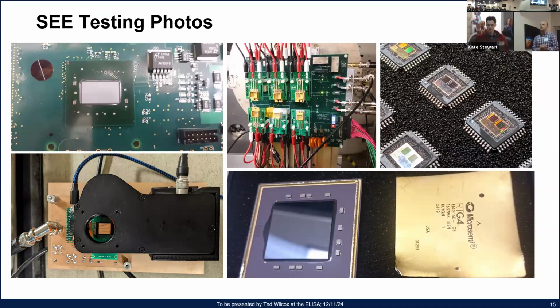At most of our domestic facilities, the energy is such that we can't penetrate the lid of the device. So we tend to delid the devices. We are operating at much lower energies than those galactic cosmic rays, which will not be bothered at all by the lid, but this is sort of a test prep phase.